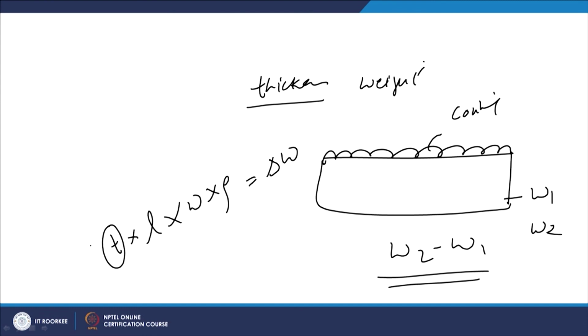So, if we have the data about the weight gain due to the development of the coating, the information about the density, and have measured the length and width of the coating, then the average thickness of the deposited coating can easily be calculated using this weight gain method.